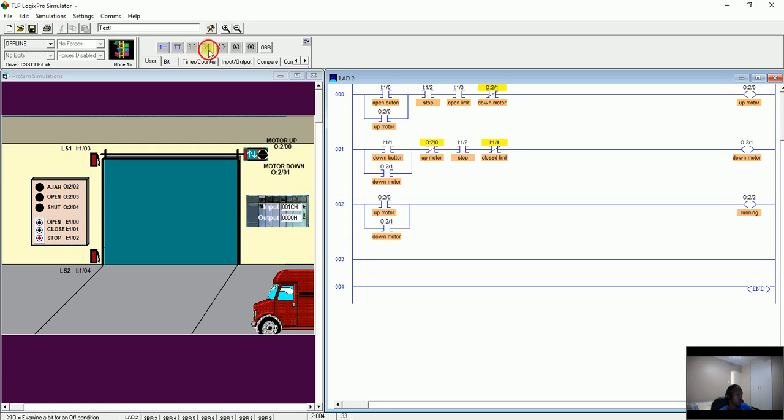On this one, it's not active when the door is fully open. So let me see. We say it's not activated, it's false. There's no power, there's no 24 volts to the card. So meaning I should use this one when it's fully open. Yes, we're right.